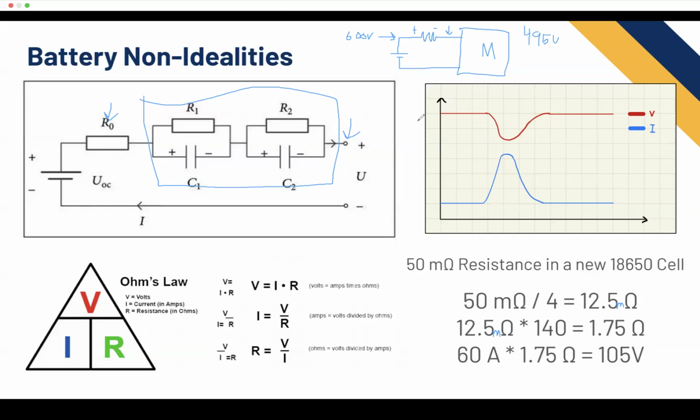The issue we ran into last year is the aluminum casing for the accumulator, right? Aluminum warps a lot more when it welds. And it was our first time doing those long pockets, so we could actually only fit 4 out of the 8 segments in there. So our total battery voltage peak was only like 300 volts or something, because it was only half. Somewhere around there. So when we would pull 60 amps and we would drop 105 volts, we were already limited.